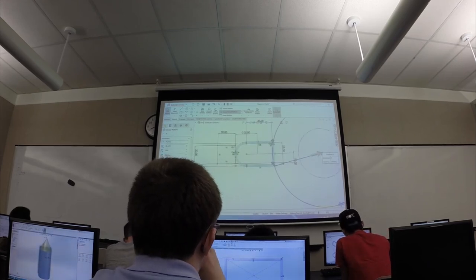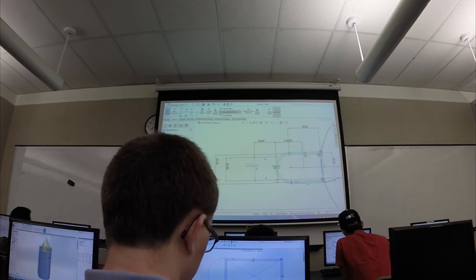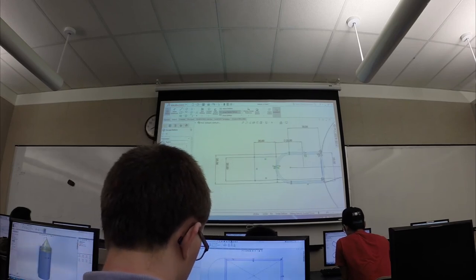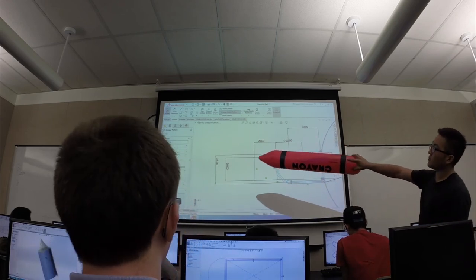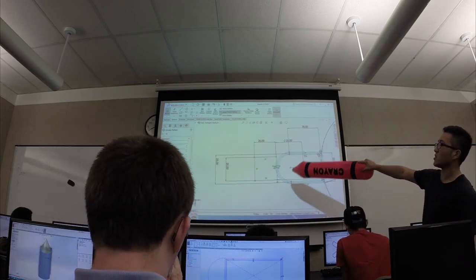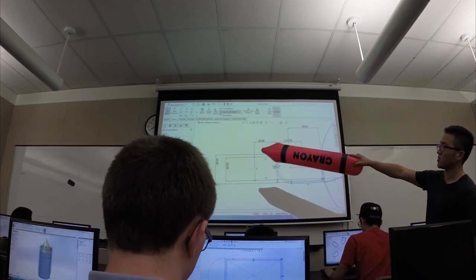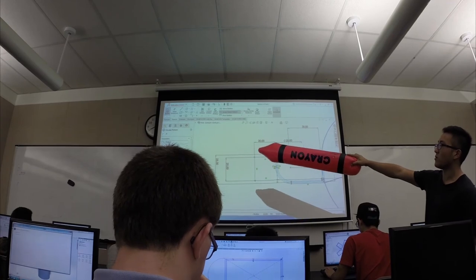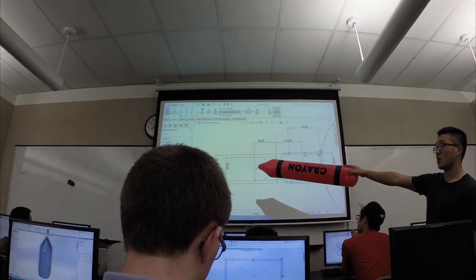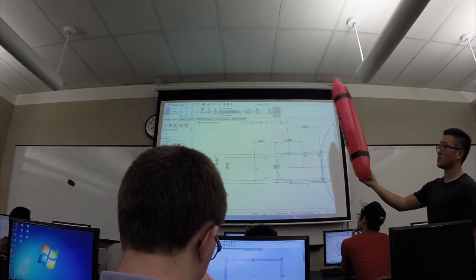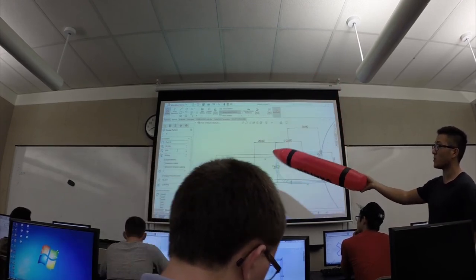Select this box as well. So it highlights blue when you selected it, right? So currently the other parameters say, okay, I want to revolve this around 360 degrees based off a circle with those X and Y parameters in that location. When you have that equal spacing box checked, it'll place each of those entities equal distance apart from each other, or at this point, I guess, equal angle apart from each other.